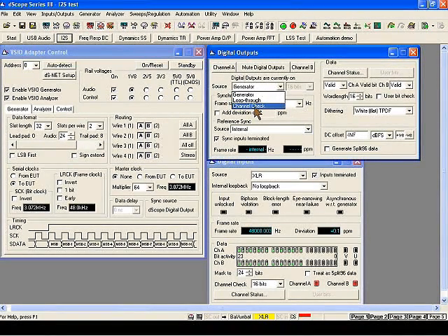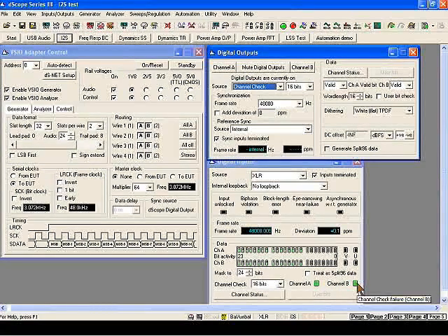this allows me to automatically check every single data bit that's being received at the input to the test instrument and verify that it is truly bit transparent. You will see that these lights have turned green at the bottom of the page here, and that is a verification of the fact that this system is behaving bit transparently as we would expect. If I just switch between the channel check sequence and the generator stimulus, the sine wave we saw, these lights have now gone red and back to green again, indicating that a second or two ago we had a failure in the bit transparency because this test sequence was not reaching the end of the signal path.